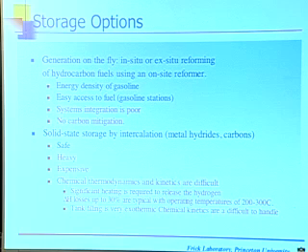Reforming takes place at about 700 to 800 degrees C because it's an endothermic reaction at room temperature. Heat it up to make the free energy negative. And the fuel cell that we're talking about runs at, let's say, 150 degrees on a good day. So you're going to take this 900-degree box, and you want to bolt it to this 150-degree box. And so there are some engineering tricks there about how you do that and keep them all happy.